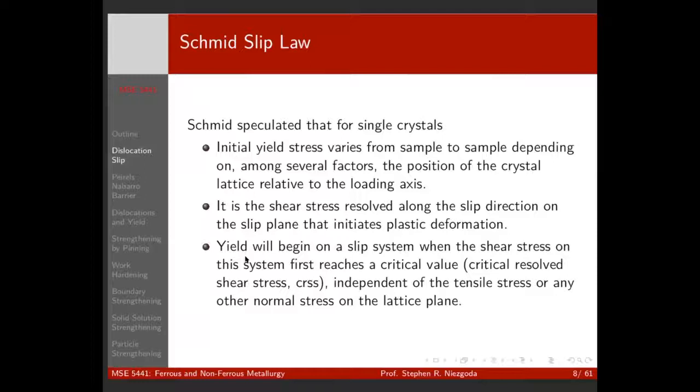So really all we care about is shear. Will a metal ever yield under a pure hydrostatic pressure? If I take a hunk of steel and put it at the bottom of the ocean, or put it in a pressure chamber, keep increasing the pressure on it, will you get yield? No, right? Because in a perfectly hydrostatic stress state, there's no shear in any direction.